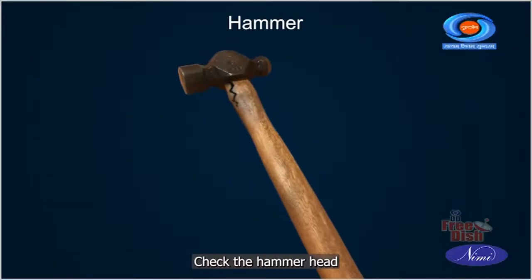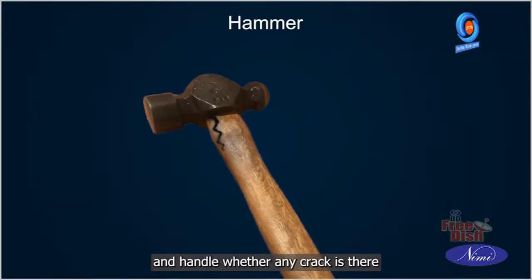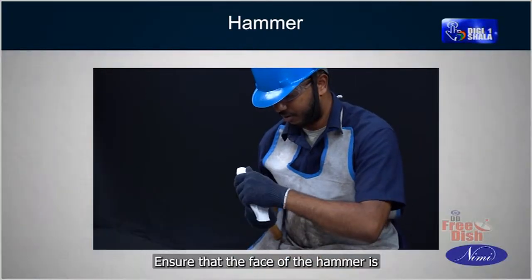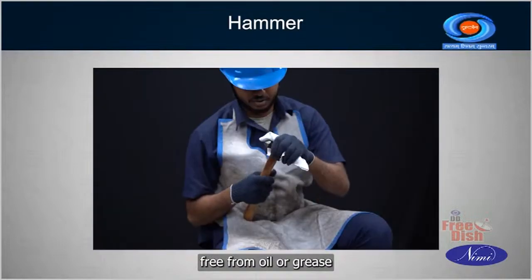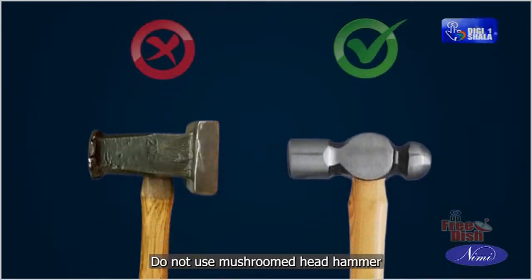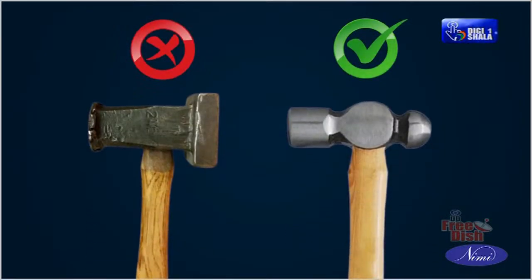Check the hammer head and handle whether any crack is there. Ensure that the face of the hammer is free from oil or grease. Do not use mushroomed head hammer.